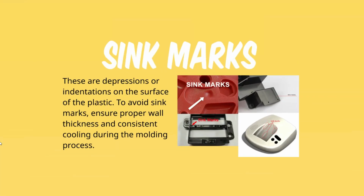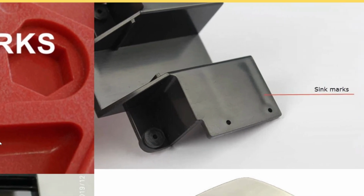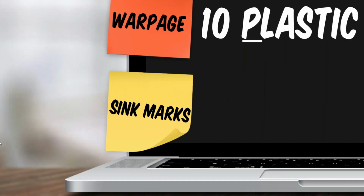1. Sink marks. These are depressions or indentations on the surface of the plastic. To avoid sink marks, ensure proper wall thickness and consistent cooling during the molding process.